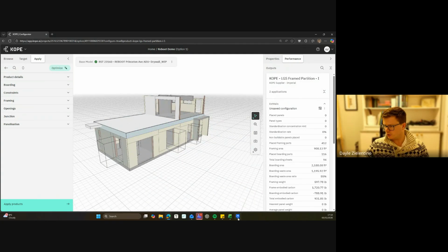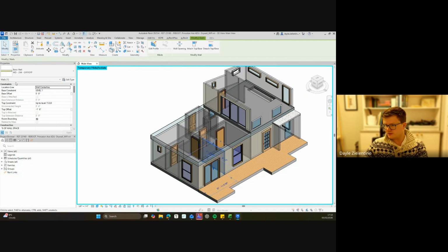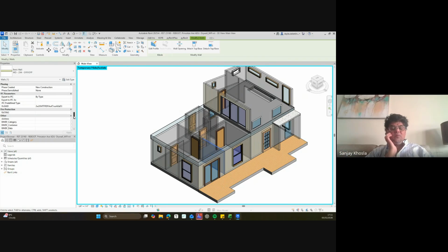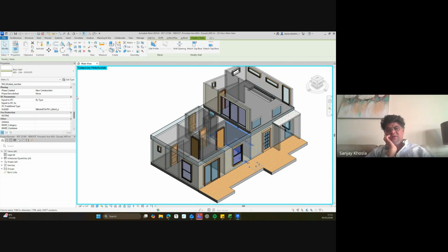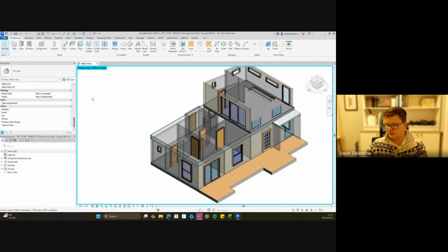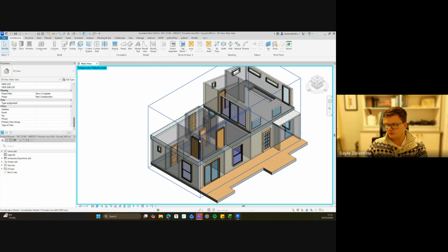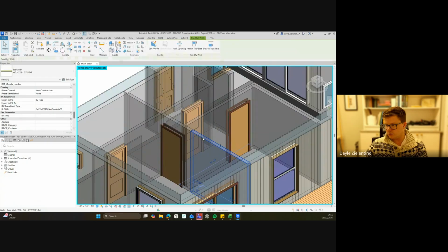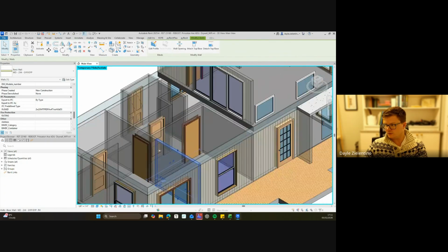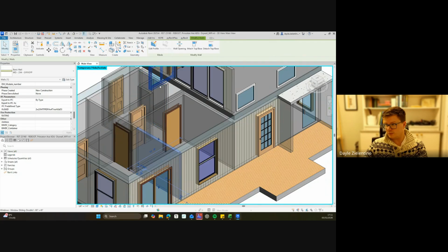No. We might be able to. I just don't know where the information was in this Revit model. So if I turn this back off, there's nothing in here that says that this is module 1, module 2. Yeah, module, we have it in our engineering drawings, but that's fine. So that's where we would need it as a data point in the BIM for us to be able to pull that out. If it's just a piece of text on a drawing, that doesn't go anywhere. We would need it in here to say what module it was part of. So typically you'd be breaking this into a twin wall if that was the case. So maybe it's these walls that are actually twin walls that go in one mod and another mod. So we would be framing those out.